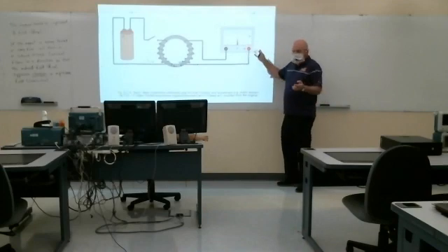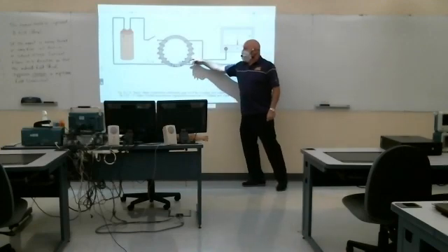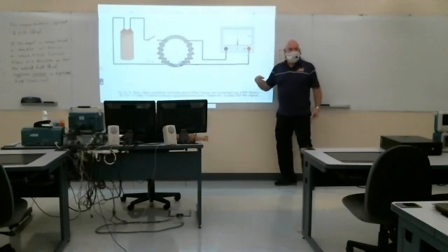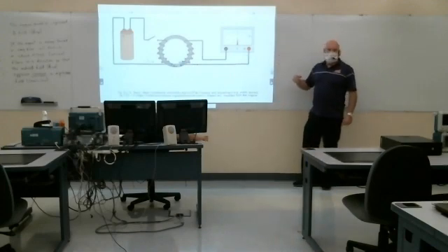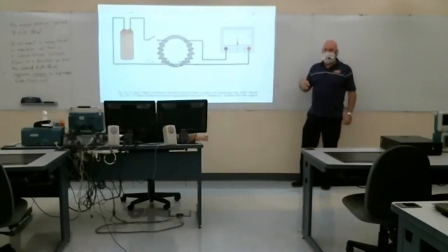Now notice here, if this is an ideal voltmeter, there may not actually be any current flow. And if there's no current, there actually wouldn't be an induced B field. So this is all just kind of a trick to help me determine the voltage polarity. Now, if there were an actual load, there would be current flow and there would be an induced B field in that direction. Now, this induced B field only exists while the impressed field is changing.